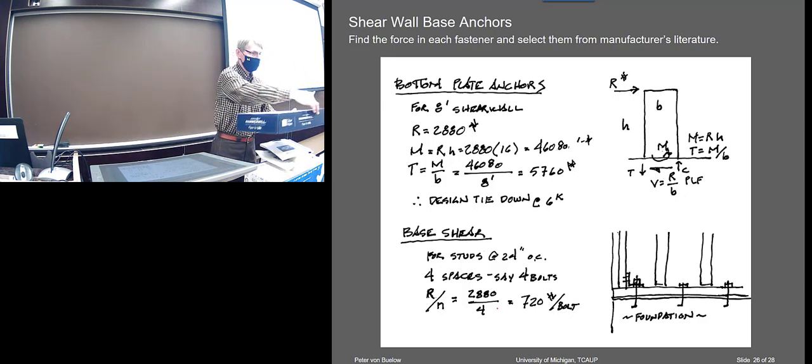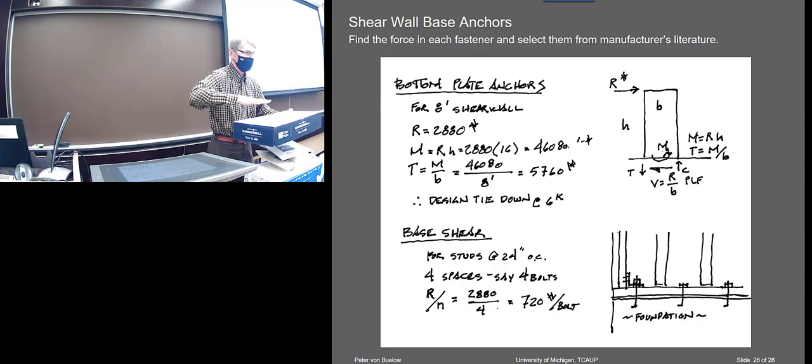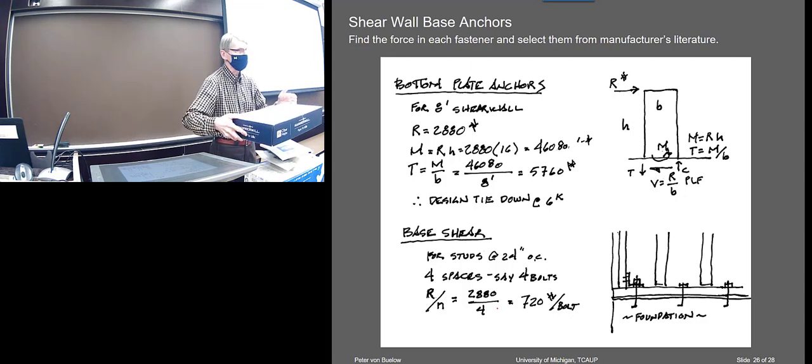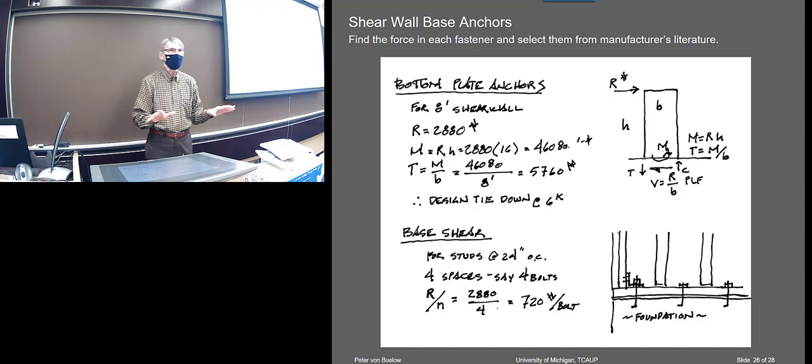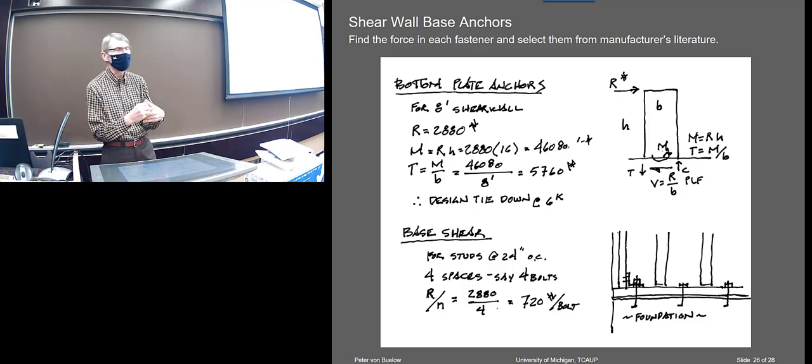shear wall. So what we did is we did this collector strut first, if the wind's going this way, right? And then we did this collector strut just now. So this has got the shear, and this has got the bending. So we did both collector struts, and they both panned out to, I think on the online problem, it just asks you pass or fail, I think. Or maybe it just asks you the actual stress, I forget.